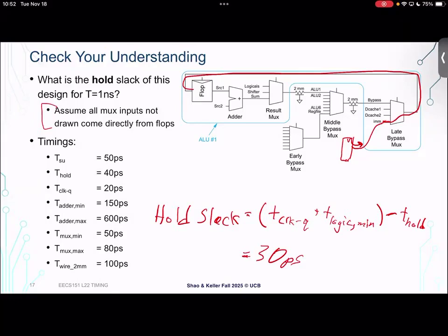Is that the point that generally we want to be really sure that the design beats the constraint? Is it normally that you want a constant amount of hold slack or some percentage? Very, very good question. It's not always going to be a constant amount. In particular, it will vary based on the voltage target or the frequency target. So you could think of it as some percentage of your clock period.